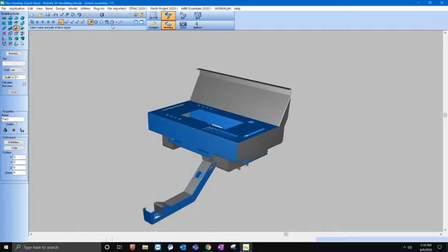And from here, before we even do that, we can check with the offline bending software: can I bend this part at the press brake? Does it have any collisions? Can I simulate it and make sure there are no collisions, and verify that the finger stops aren't hitting and crashing into the parts, between part and tooling, and part, tooling and machine? So this is where you come to do that.